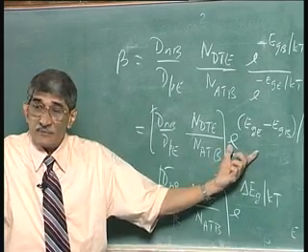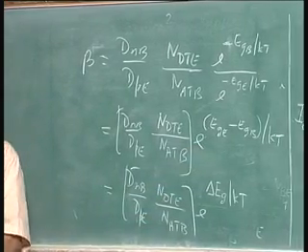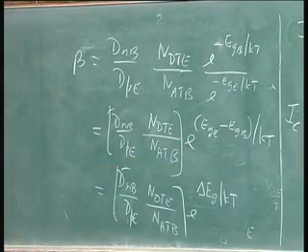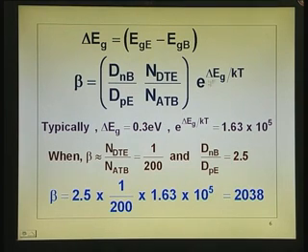So, you get a big factor multiplying this, which gives you the ability, if you choose the band gap of the emitter larger than that of the base, see the numbers are here. If you take a look at whatever I have written on the board there, this is the thing. What we are trying to tell is, if EGE is larger than EGB, this is a large number. If this is a large number, I can keep the beta high even if you reduce NDE. Now, you can see I have chosen a number to illustrate what sort of beta you can get by taking delta EG equal to 0.3 electron volts. Make the emitter that of aluminum gallium arsenide, make the base that of gallium arsenide.